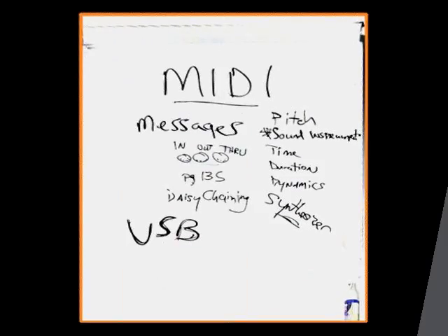And for a while there, in the 80s and the 90s, computers had what they called a parallel port. A parallel port meant you actually had a lane for each bit. Let's say they were running 8-bit computers. You actually had 8 wires in the cable. You had this thick cable and an 8-pin connector. Then they went to 16-bit, and you had 16 wires and a 16-bit connector. They were transferring the information 1 bit at a time in its own lane. That seemed like a good idea at the time, but can you imagine a parallel connector for a 64-bit computer?